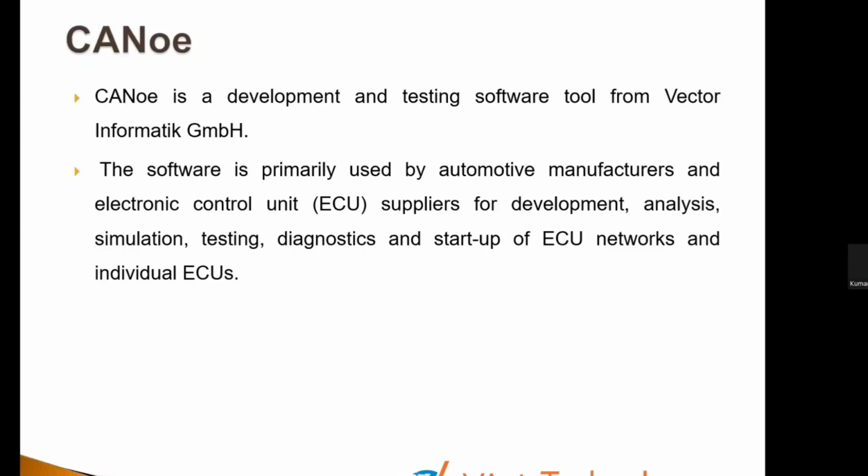If Volvo or GM or Volkswagen, whoever has given the order for the instrument cluster, they give the specification, how many times it has to be tested and what all needs to be seen. So in CANoe, you write a test script using CAPL programming to test it.